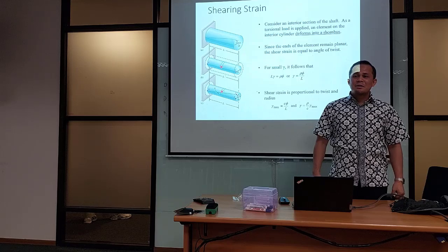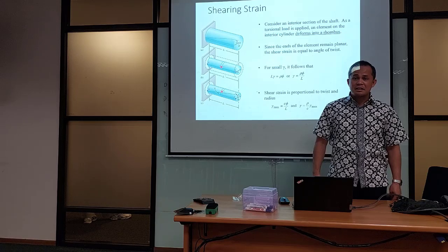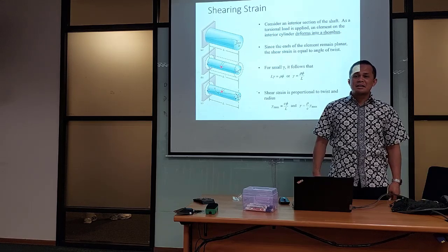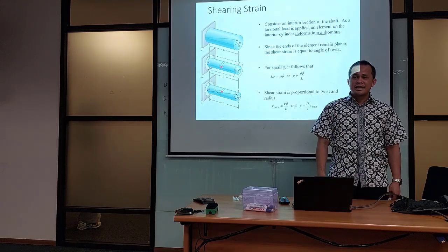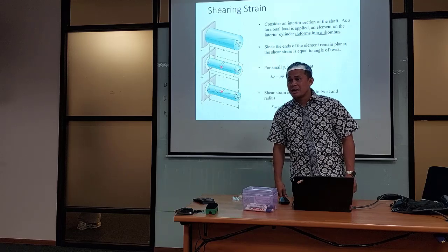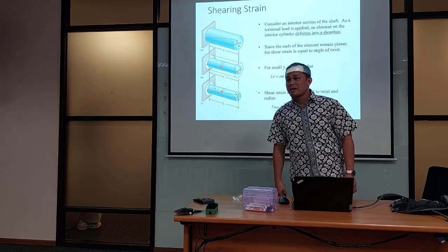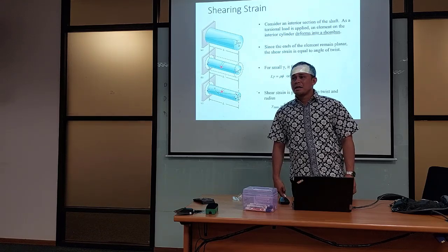Twister. So, Jarvis, where's the location of zero strain? Center. Center, in other words, if it is a shaft, what do we call the center? The axis. The axis of a shaft, no stress. Most relaxed. But the most stressful, Sean Nabil, located where? The edges of the shaft. The edges wrong. Where is the farthest? Surface. Surface? Correct.